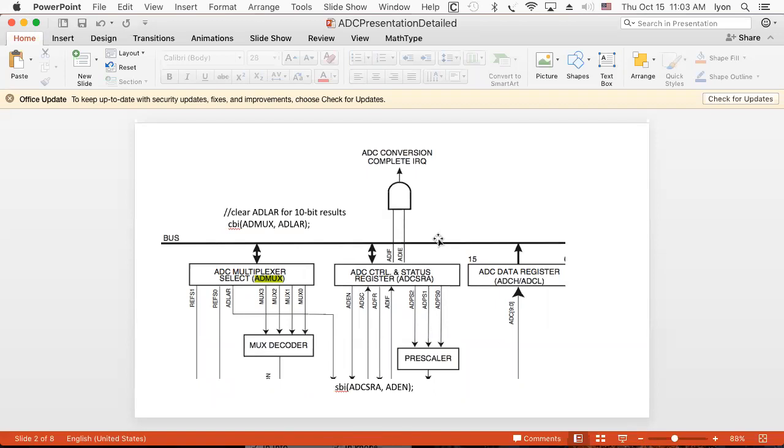So let's look deeper into the ADC converter now. We can see there's a bit of logic going on here. There's this thing called ADMUX, which is the analog to digital converter multiplexer select register. The register contains perhaps 4 bits for multiplexer inputs, but it also has other things, ADLAR, REFS0, REFS1. Now, what's that about? There's this other register here called the ADC control and status register A, and yes, indeed, there is a B, and it has things like ADEN and ADSC and ADFR and ADIF and all these prescaler inputs, which we were playing around with yesterday. And this is stuff that we have to learn about.